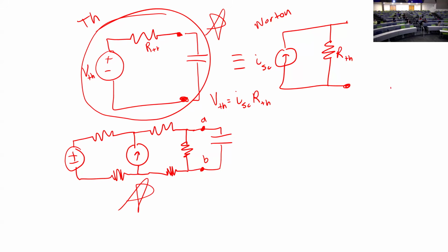Okay, yeah. So basically, the goal is to simplify it as much as possible, and then you can add in that component that you're looking for, and then just solve that. Yeah, that's exactly right. So instead of having all these different resistors and a current source and a voltage source, what if, this is a complicated thing, but if I'm only looking from two wires, I'm only really going to see a source and a resistor, right? And whatever that equivalent resistance ends up being, we have to find. But yes, we call this component over here that we plug in our load.